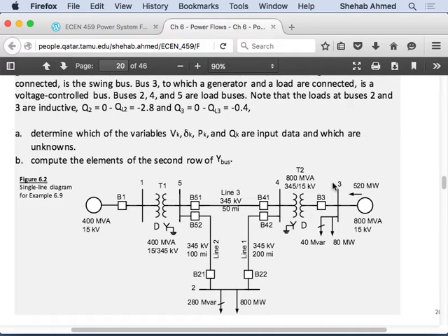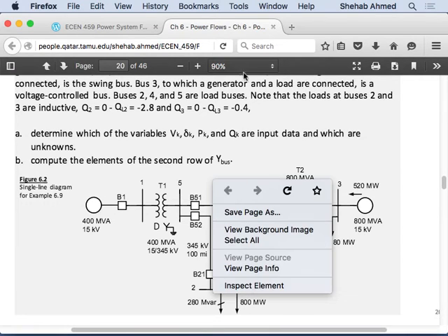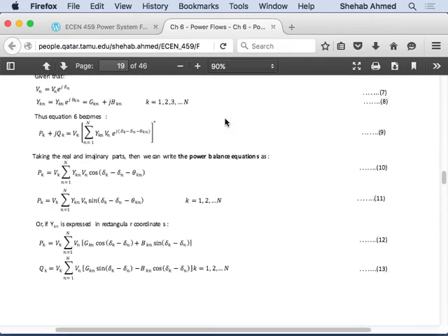So yeah, I forgot to mention something. So we came up with the real power equation and reactive power equation at every bus K, right? At a load bus, you can use both equations because you know the real and reactive power. You have to know the left-hand side to be able to use the equation, right? If you go back to the equation we have, what did we do?